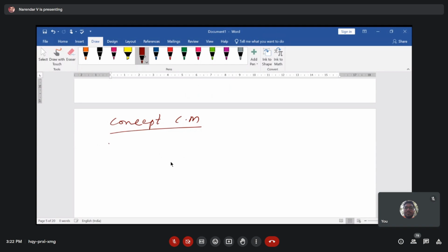The first thing we have to do is build a reference current that is referred to as a golden current source, and this golden current source is temperature independent as well as insensitive to the supply voltage.